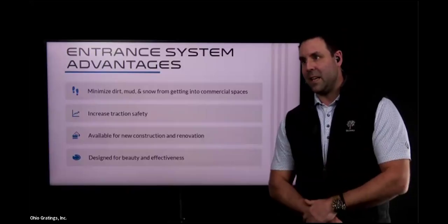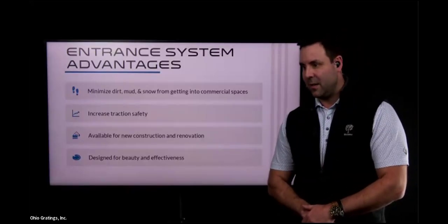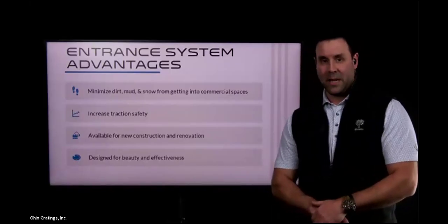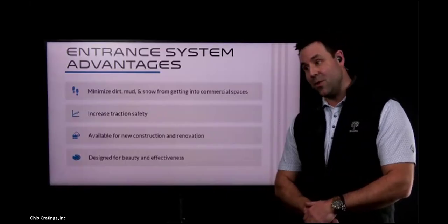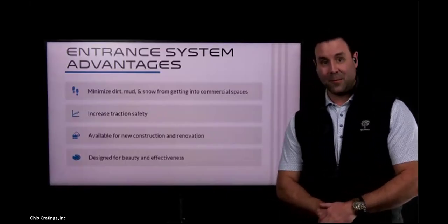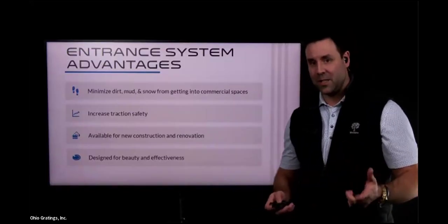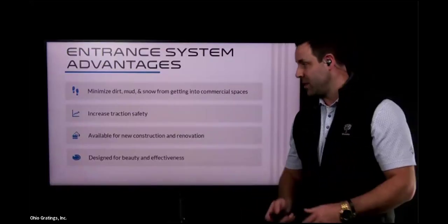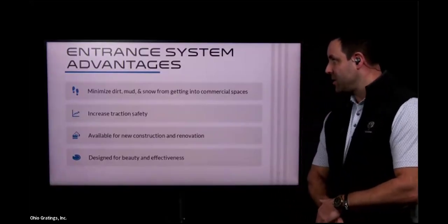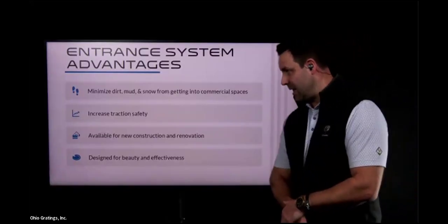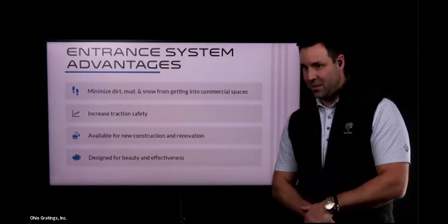I keep going back to thinking about public schools in the Northeast or New York City, when you have situations where patrons, students, and staff are entering the building out of a snowy environment into the tiled floor interior, and there is that transition point. So it does help with increasing the traction safety at those transitions. And then you do have entrance system advantages in the sense that they're available for new construction and for renovation.